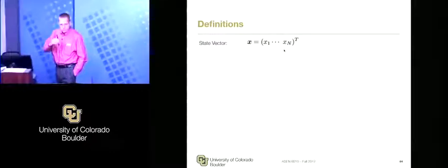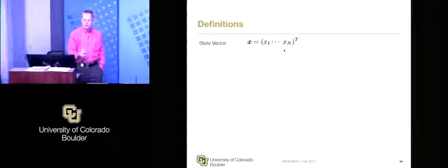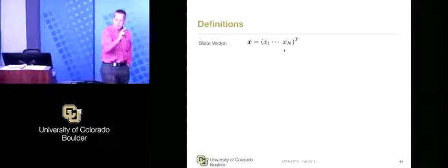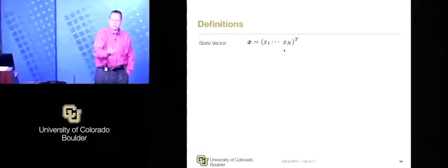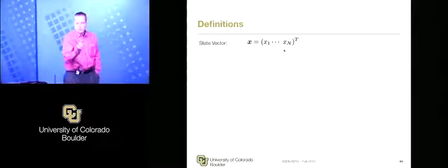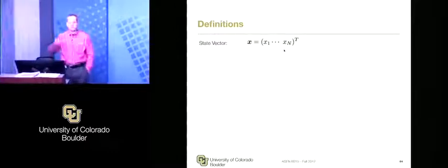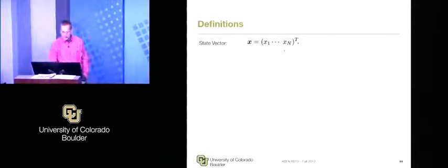6 in this case. We need 6. So for a rigid body, it's 3 degrees of freedom, but it's also a second order differential equation. All mechanical systems are second order differential equations. So you've given me 3 for the attitude. What's the other thing we're missing? Angular velocity. Yeah, which we tend to use omega. We don't tend to use MRP rates or quaternion rates. We use angular velocity. So that's what would be in there.